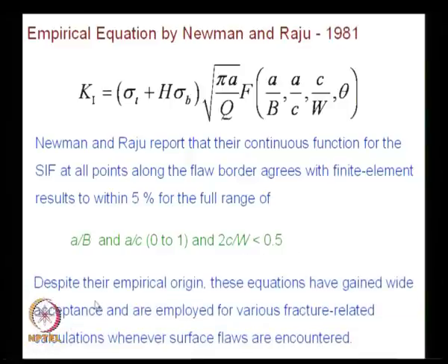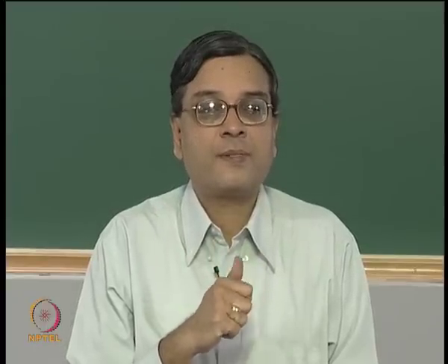And you have to note, despite their empirical origin, these equations have gained wide acceptance and are employed for various fracture related calculations whenever surface flaws are encountered. So, as far as surface flaws are concerned, you can always go and look at the empirical relations of Newman and Raju and use it for your calculations. That level of confidence the fracture community has placed on their results.